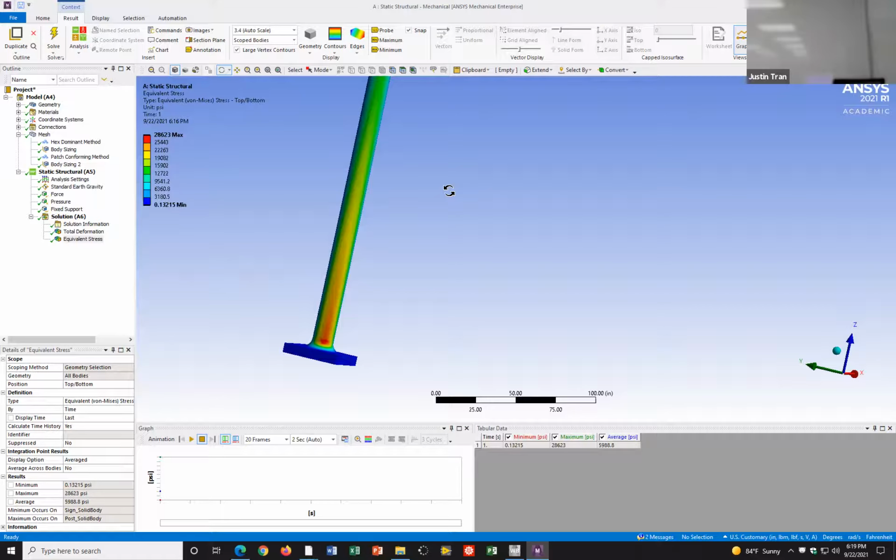I'm planning a refinement right there, where the connection assignment is supposed to be, but my refinement for this one is just faces. I want to include this line too and then this area. You can do control clicking. You can click on this face and then switch to this one right here. I think if you select that face, it should automatically do that edge too, since that edge is connected to it. But it's not refined. Try just choosing that edge or making another refinement just around it. It's fine to make more than one refinement at the same time. Okay, this is amazing, right?